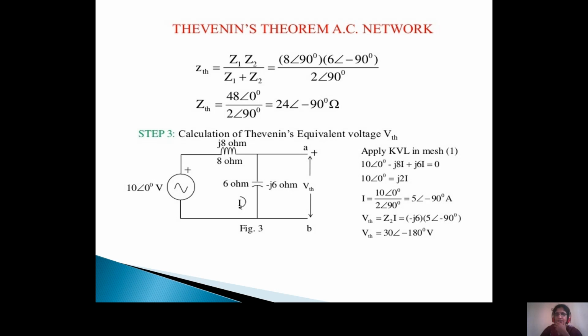In an AC circuit, when there is impedance, they given simply inductance, that is 8 ohms, but you have to convert it to inductive reactance, that means we put j8. When there is a capacitance, it will be only 6 ohms, put minus j6. Why negative? In the inductance, R plus jXL is the impedance for inductive nature, or minus jXC is represented for the capacitive nature.